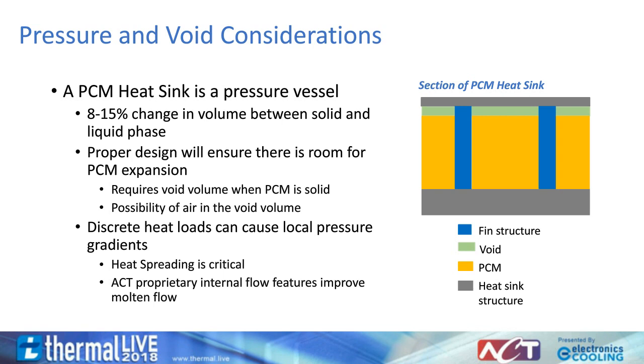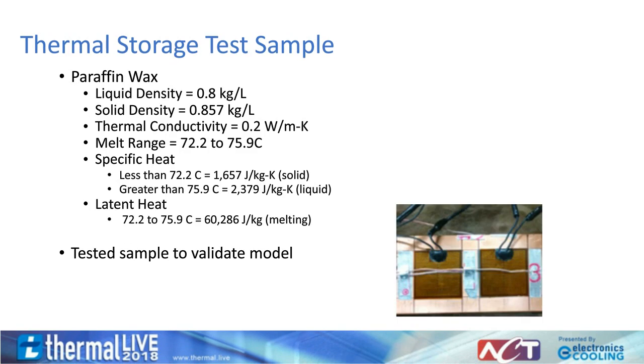Here is an example of a typical PCM application. In this case, after selecting the PCM, determining the required volume, and designing the enclosure with proper fin and wall structure, it's time to manufacture and test the PCM. This slide shows a tested sample with the estimated properties shown to the left. Note the large change in specific heat for the different temperatures.